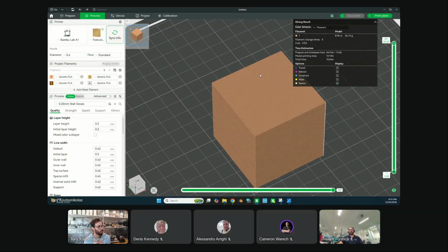And that is why what I would usually recommend is, if you're going to use a texture to hide layer lines and you create this visual appearance, you can increase your layer height to accommodate for the increase in print time. That's what we tell people that do this part, and people that do automotive stuff as well.